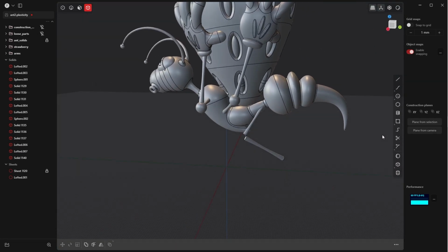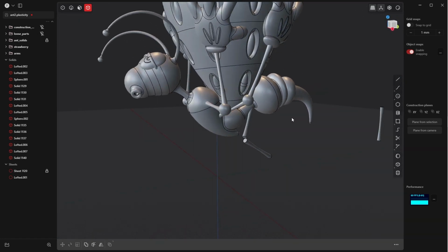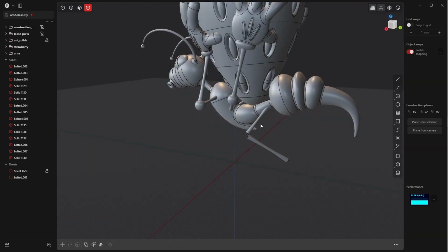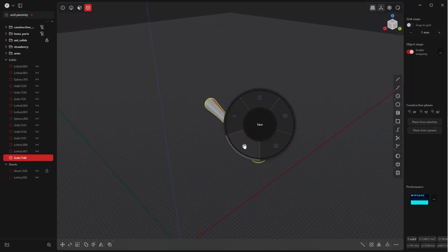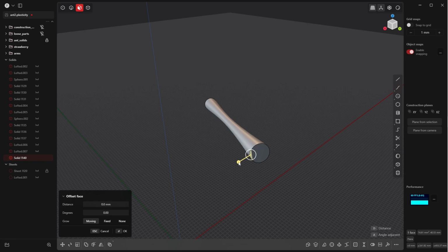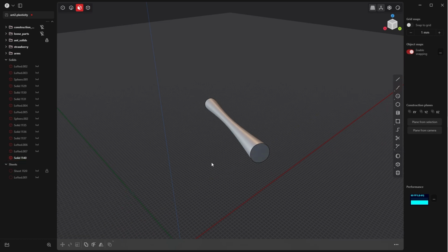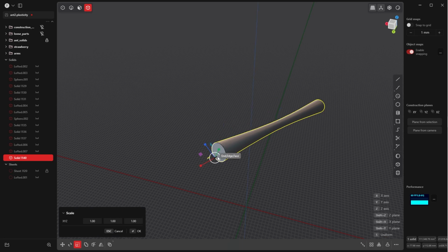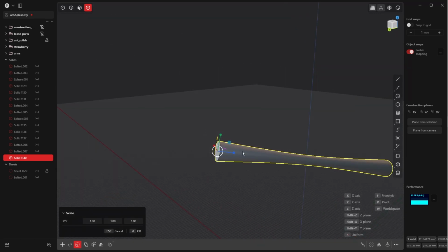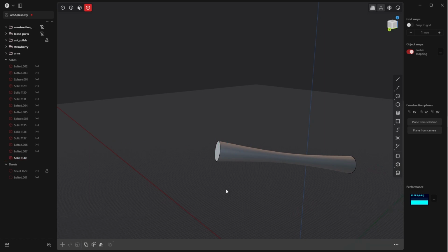Maybe that's okay. We don't need this one to be shorter. Maybe we will do this one longer, so there is an obvious difference between these two limbs. But let's see. First of all, isolate this one also, pressing Shift H. Here's also the cut. I mean, we don't even need to get rid of it because it will intersect with the body anyhow. Go to Solid View, press S. Snapping is enabled. Press V for changing the pivot. Let's pull this one also in. And we had the value of 0.75. Bring back the rest.